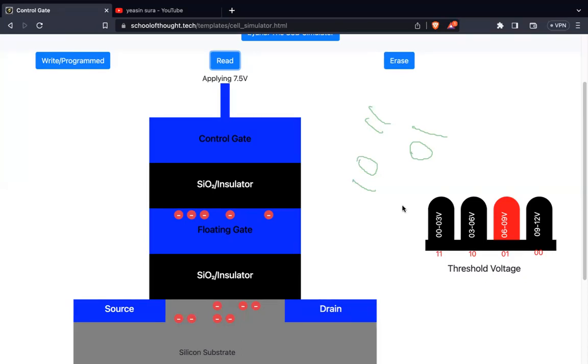So we have to distribute all the information in a way that all the transistors are written almost a similar number of times. Let's say there are 2 transistors. If this transistor has been written only 1 time, that transistor will also be written only 1 time. And if this transistor is written 500 times, that transistor will also be written 500 times. So they will be dead together. In that way our SSD storage will not be lost, it will not actually decrease.